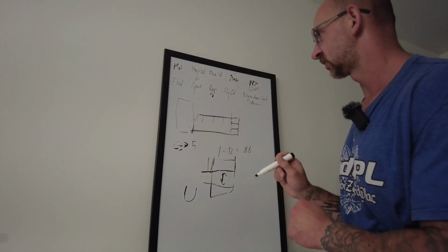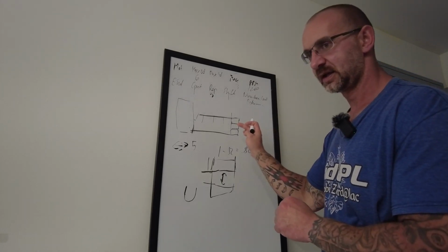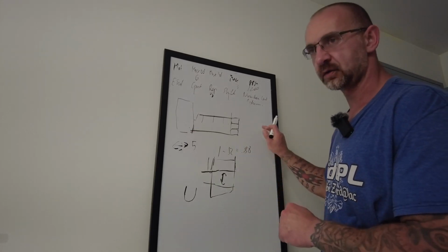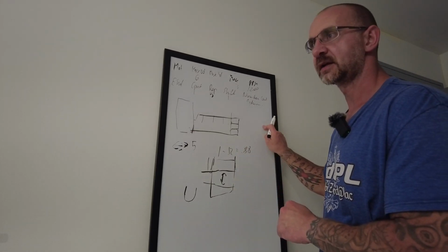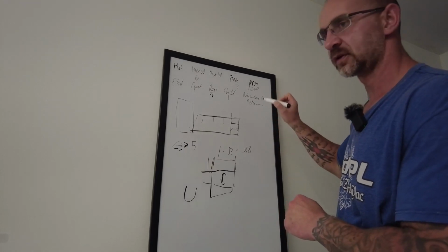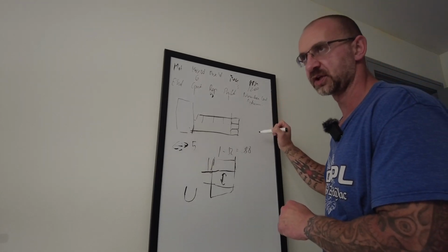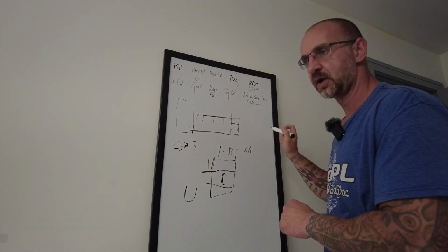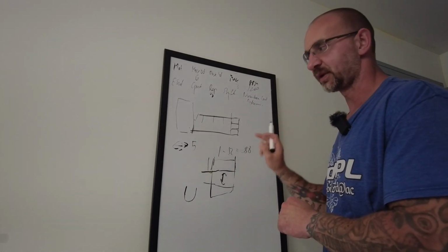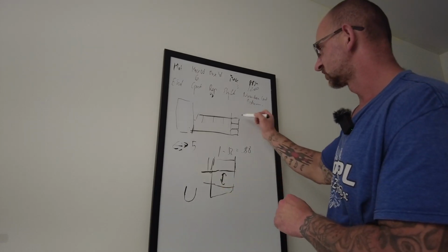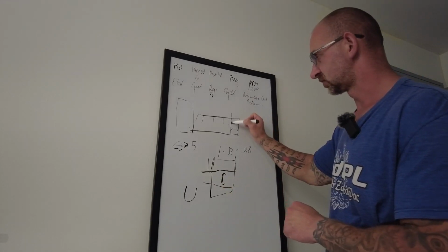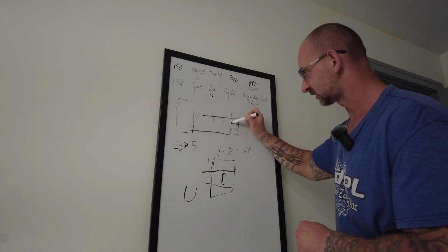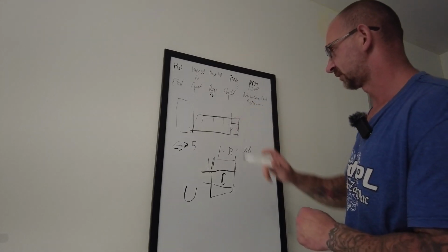So usually, if I'm going to have to hit the part, or remove it, or break off the part, I go to my facing, where at the end you have your M codes. You put it where you usually put M8. You can put M0 for a stop, or M1 for an optional stop, but then you have to press the optional stop. So she will come down, cut off that ring, but it's still going to be sitting there.